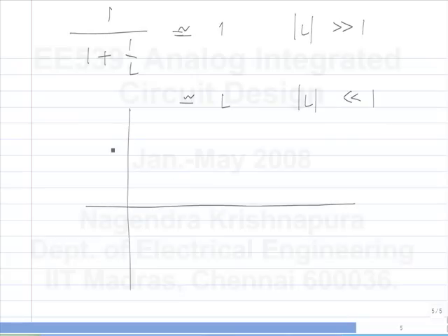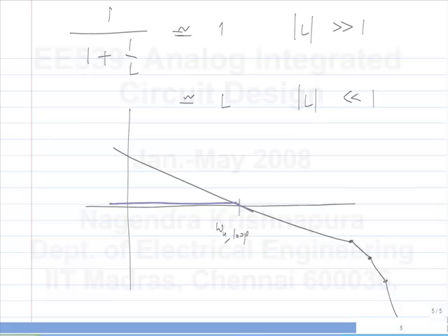So if you have a loop gain function like this, where all of the parasitic effects are at high frequencies well beyond the unity loop gain frequency, then the resulting function will simply follow a first order type of behavior until you see these parasitic effects. Okay. So you do know that if you place all of these parasitics very far away from unity gain frequency, you will get more or less a first order behavior. The question is what happens when you get closer to this.